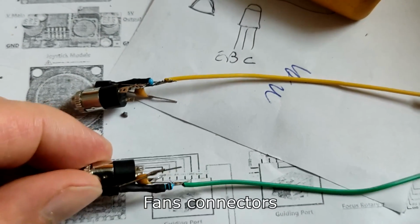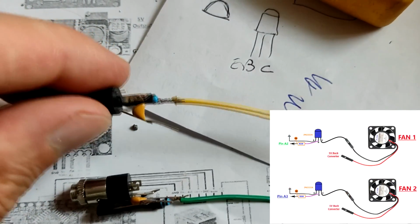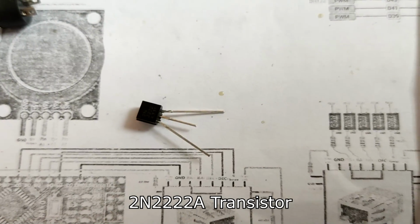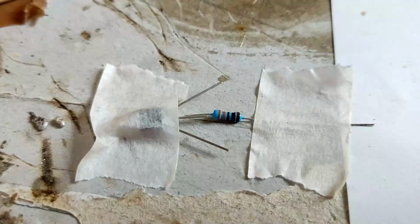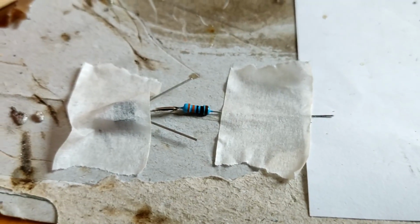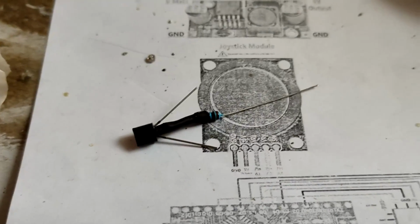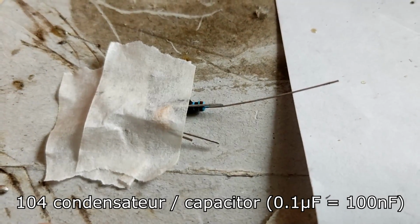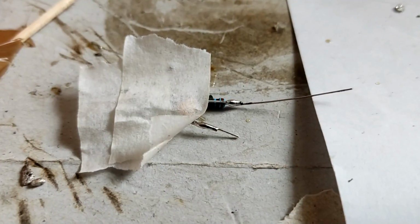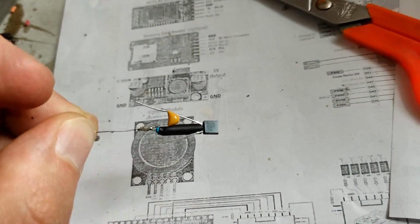To make the fan connectors we need some components. As you can see in the wiring diagram, we need a transistor, a resistor and a capacitor. I've cut the transistor middle pin, then I soldered the resistor on it. Then I used a little piece of heat shrink sleeve to isolate the pin. After that I soldered the capacitor on the transistor. You can see after I removed the tape, it's soldered between the resistor and the emitter of the transistor.